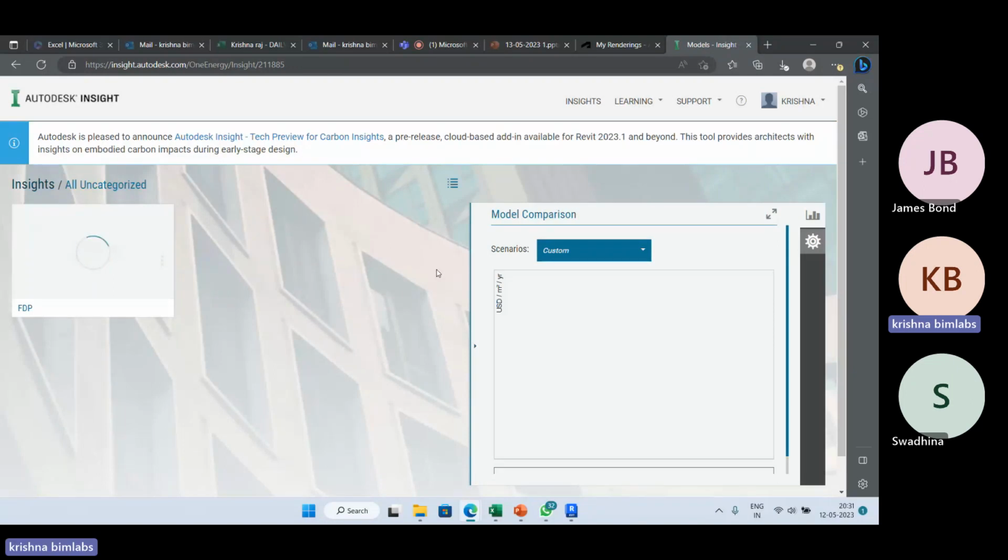Each wall's window wall ratio you can adjust. If you want to increase the windows, suggestions from 0% to 100% will be there. You can adjust the value to the actual value. 100% means the whole wall will be window, which cannot be done. It will be around 25%, you can suggest that there. Okay, I'll show you, it's completed.